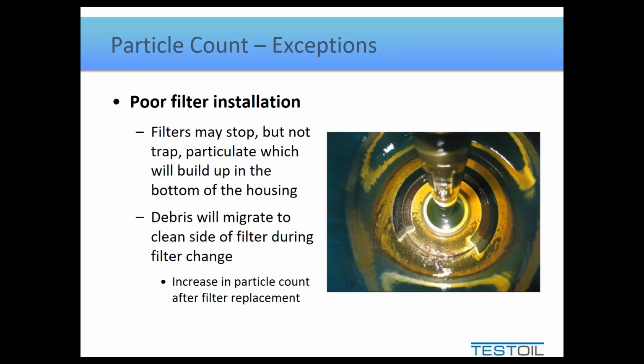And therefore, when you install a new filter, what you're going to see initially is a jump in particle count, because now you've got all that particulate, especially large particulate, on the clean side of the filter that will have to take one ride through the system before it hits the filter and gets stopped again.